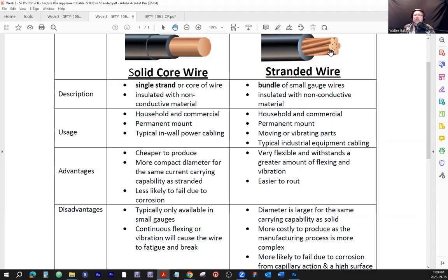That's why when you see wire strippers, you're going to see two grooves for stripping solid core or stranded. You're going to see a groove that is labeled 14, for example, gauge 14. You're going to see, for example, 14 solid and 14 stranded, and the 14 stranded is going to be a slightly bigger groove to accommodate the bigger physical size.